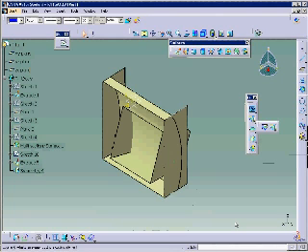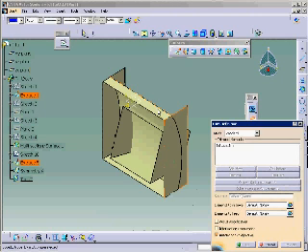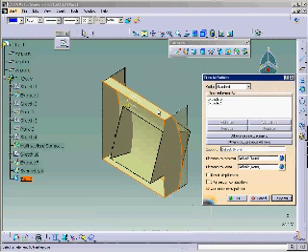After creating the surfaces, you need to trim their unwanted portion using the Trim tool. To do so, choose the Trim button. Select the right extruded surface as the first element and base feature as the second element. The names of both the selected surfaces will be displayed in the trim elements selection areas. The preview of the trim surfaces is displayed in the geometry area. If they are not the same as required, you need to flip the directions to trim the other sides of the surfaces. Now choose the OK button.